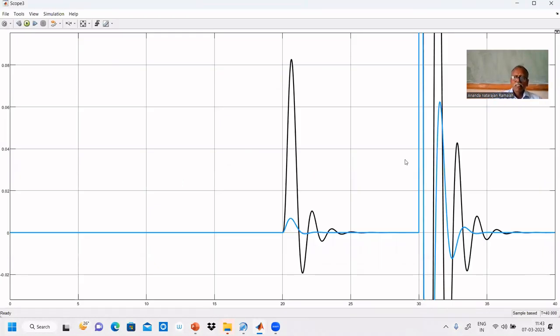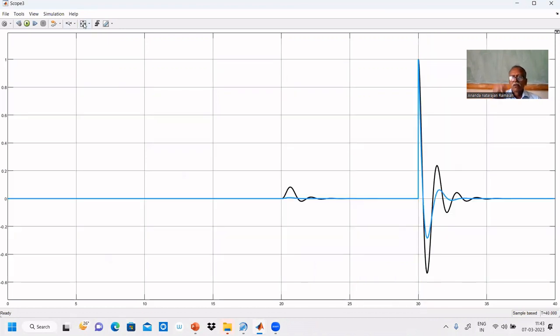In that case, for change in inlet temperature, change in TI, you consider like that. Both have the same amount of overshoot. But settling time, if you consider, cascade control settles better. The overshoot alone is the same in both cases, but the settling time is better. So in both cases, the cascade control gives better dynamics. That we can see from this simulation.